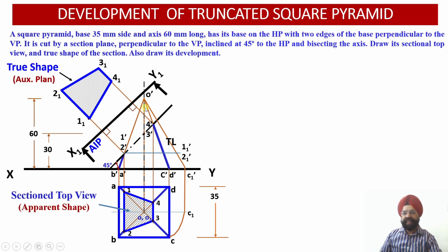So once again, since I am not using this length to draw the radial distance over here, because I have worked out the true length radial distance, similarly the true length radial distance for these points of intersections also need to be evaluated. So this is the radial distance corresponding to the apparent length.